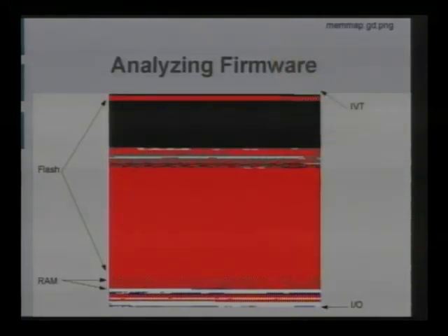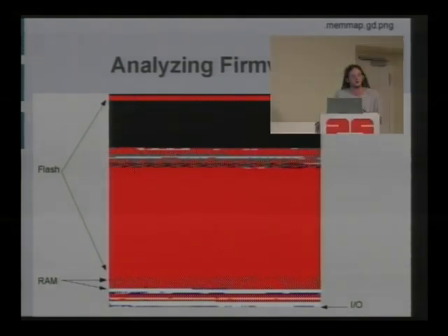So I dumped the firmware of the MSP430 and I ran it through an analysis tool that I've built called MSP430 Static. Firmware analysis tools, or I suppose it's not firmware in the 32-bit range. So on a PC, you have IDA Pro. And IDA Pro uses lots of very sophisticated algorithms to search in anything approaching a reasonable amount of time.